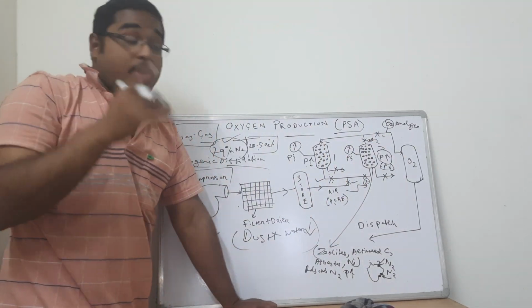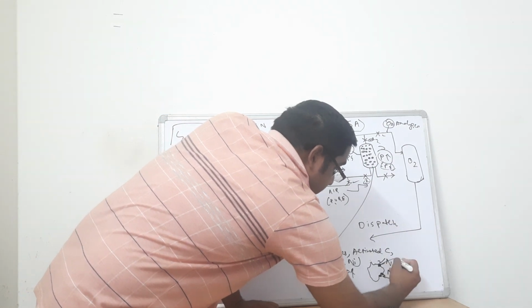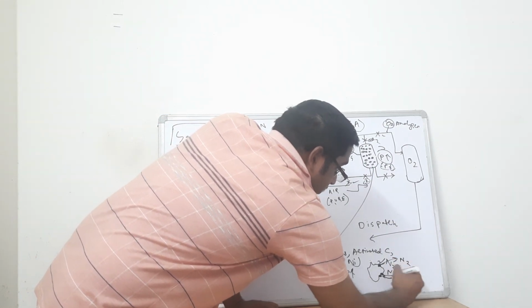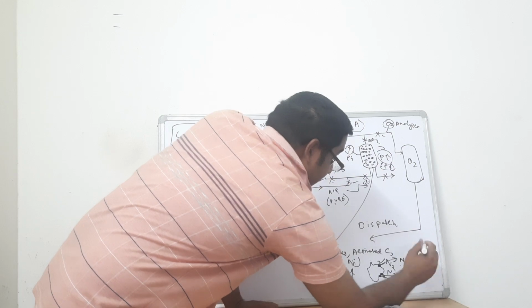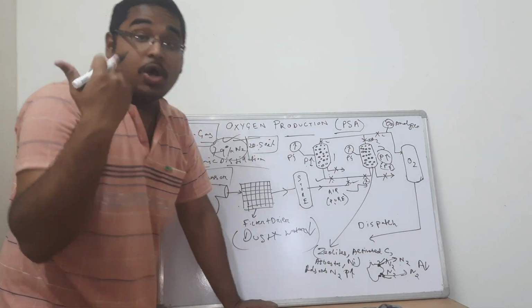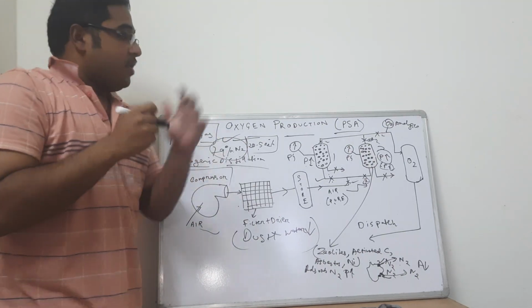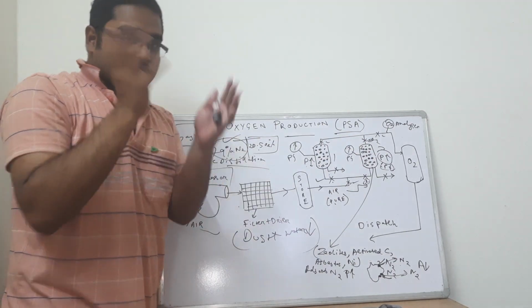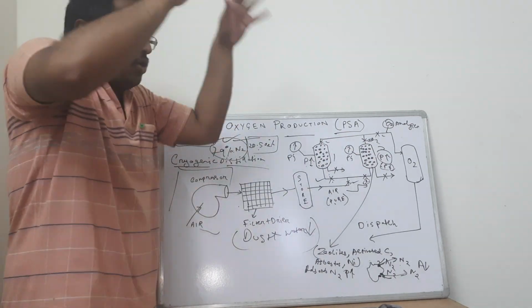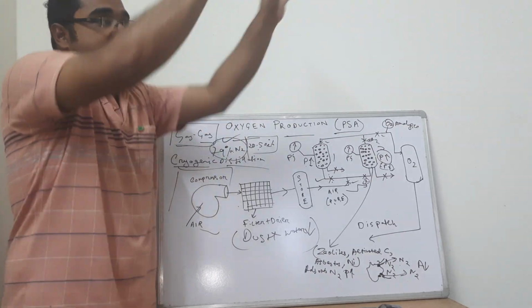And as the pressure is dropped, I told you, under low pressure, my friends, this N2 tends to go back. N2 tends to get released under low pressure. Whenever the pressure is low, the desorption cycle takes place, or the adsorbed material tries to escape out from the activated pores. From the pore structure, it gets dissolved because the pressure is maintained till then, and you release the pressure, the nitrogen tries to escape.